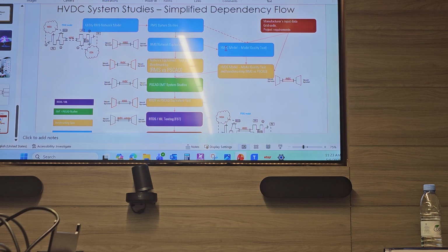Saudi Electricity, in order to check model development behavior, have a list. There is a procedure, and they tell contractors, look, simulate this, simulate that. After a fault, your system should be stable. The curve should not go more than 10%, 5% of the set value. There is a description, a standard. Yes, standard.